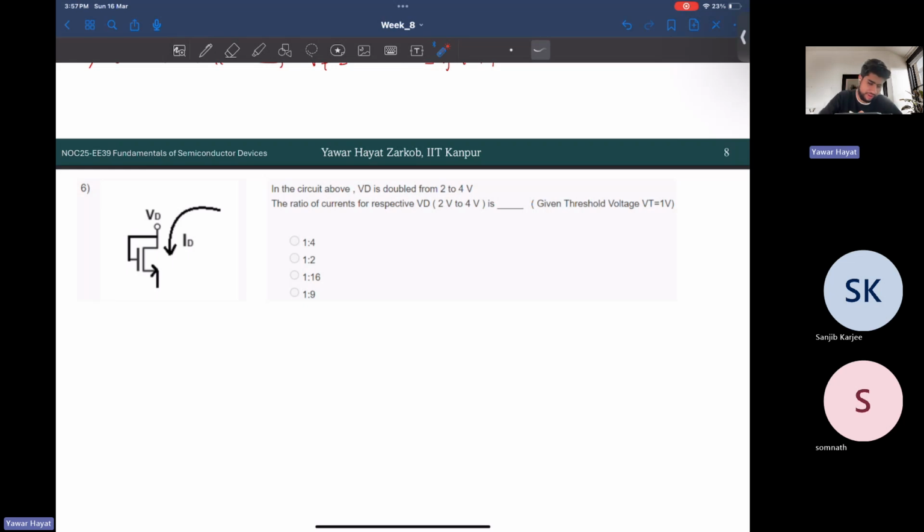Firstly, we already saw in the introduction such kind of a MOSFET. What is this MOSFET known as? We discussed it, right? Which two terminals are shorted? Diode-connected MOSFET. And what is special about a diode MOSFET? It is always in saturation region. It's in saturation, right? So I'll write the following.